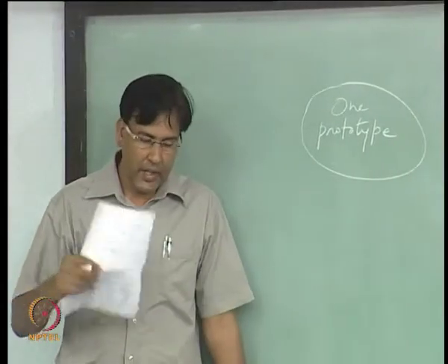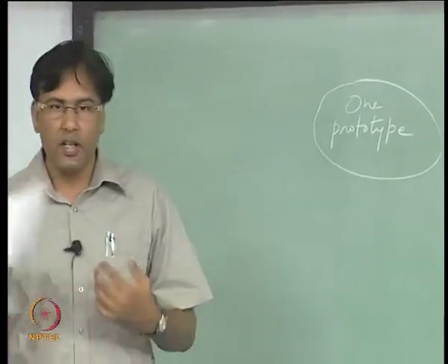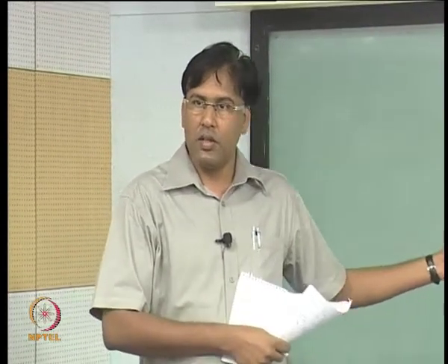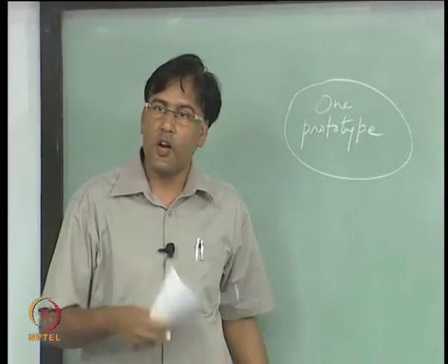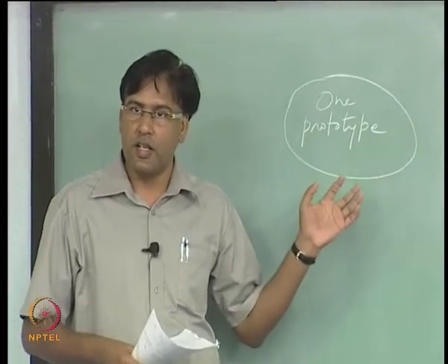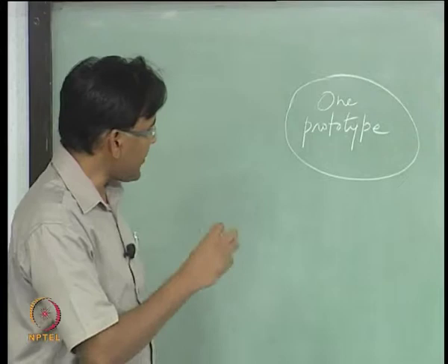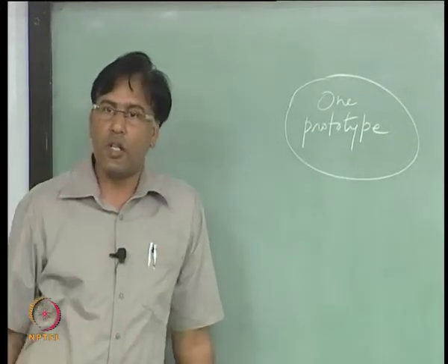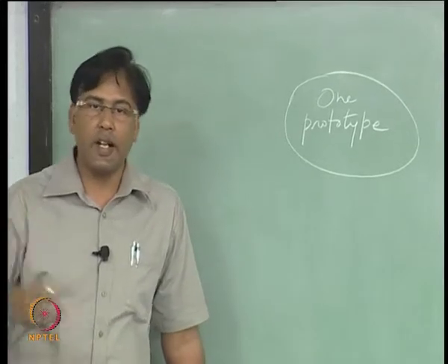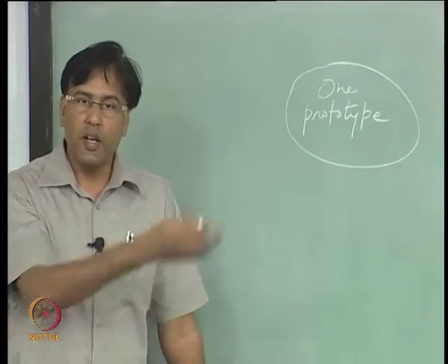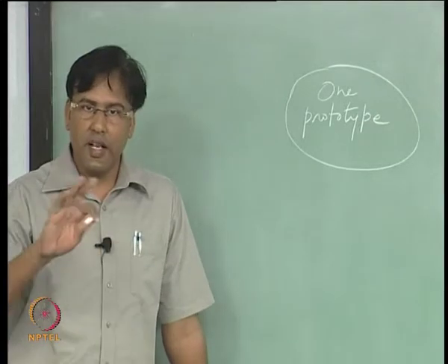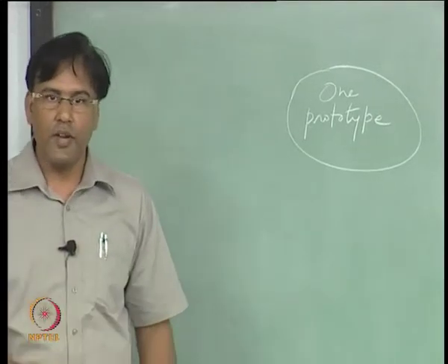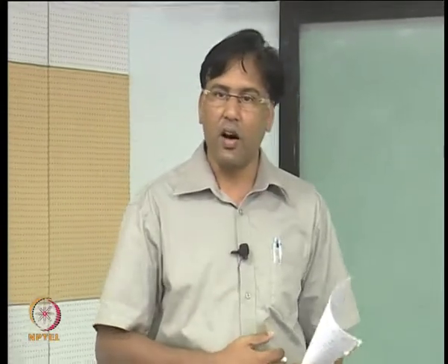The performance of the aircraft, or the behavior of the aircraft in air, is going to depend upon the configuration and the aerodynamics around this configuration. So, now after you have done this, either you build a scaled model and put it in the wind tunnel and measure all the derivatives. That is a tedious task, isn't it, finding out all the derivatives at all flying conditions.